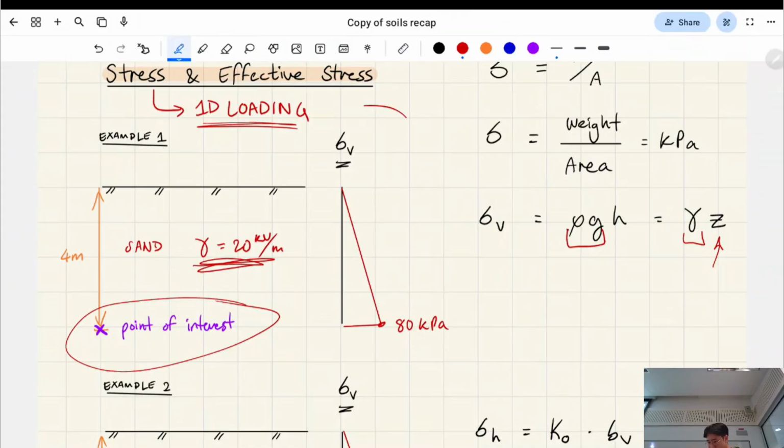You can graph it vertically, plotted vertically. This is why I'm saying it's similar to a bending moment diagram and shear force diagram. It linearly increases as you go down, so it'd be 80 kPa of essentially pressure, but we call it stress, stacked on the soil there vertically.